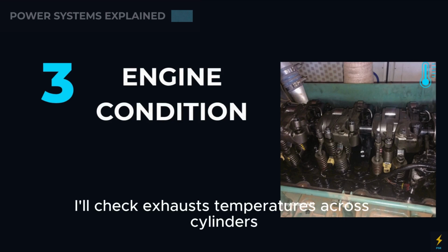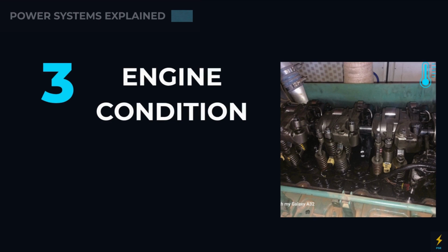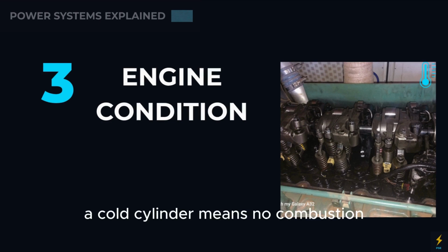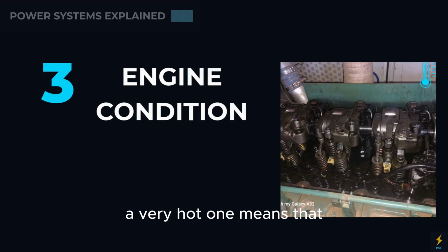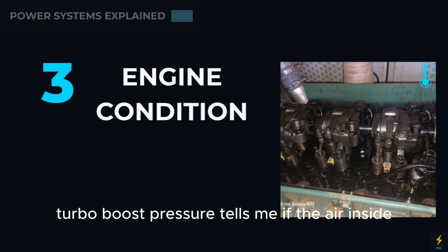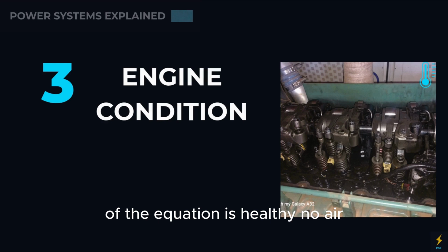I'll check exhaust temperatures across cylinders. A cold cylinder means no combustion. A very hot one means that cylinder is carrying extra load. Turbo boost pressure tells me if the air side of the equation is healthy. No air, no power, no frequency.